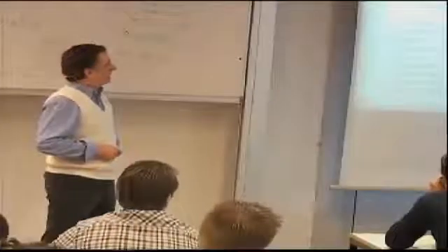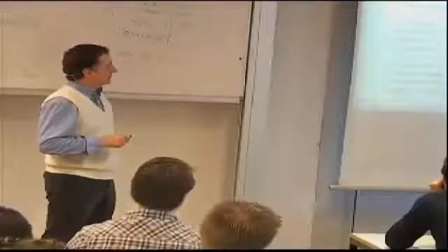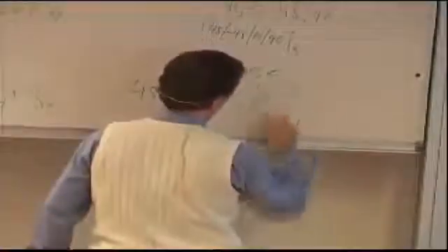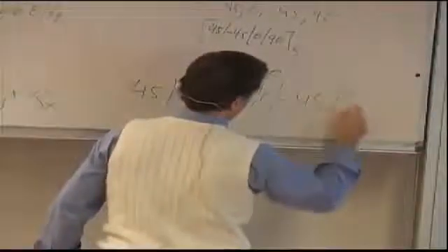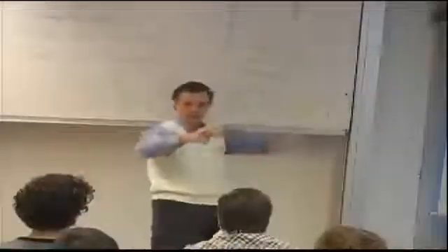So, we have a rectangular laminate, and this is the stacking sequence, 45 minus 45, 0 symmetric, which means 45 minus 45, 0, 0, minus 45 and 45, and that's the entire laminate. So there's another 6 plies. And it's under pure torsion.